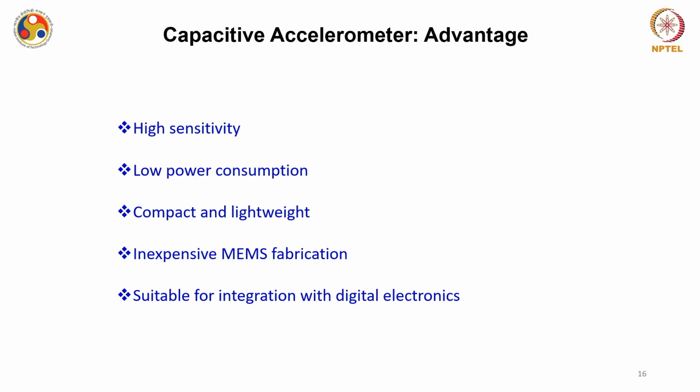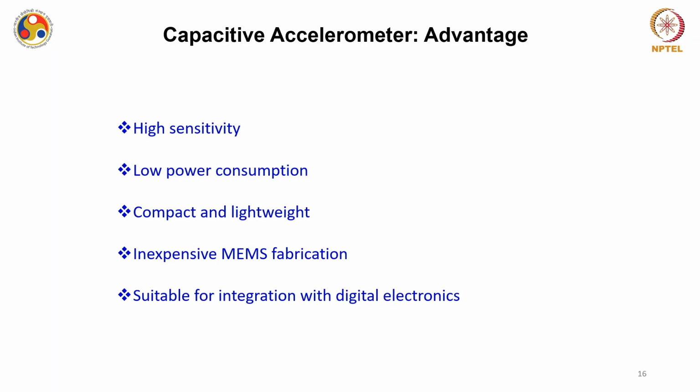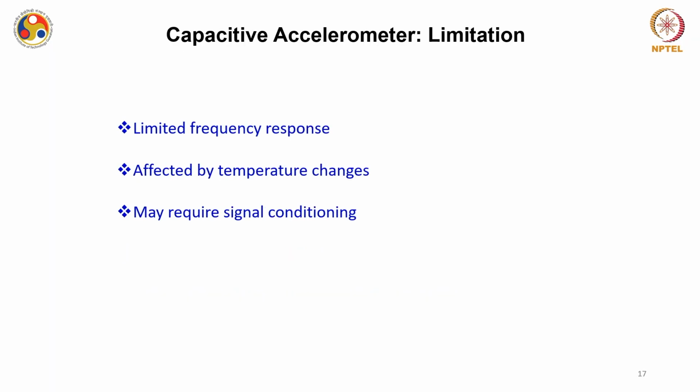There are several advantages associated with capacitive accelerometers, like their high sensitivity and low power consumption. They are compact because these are MEMS devices, and of course lightweight. Since batch fabrication is possible, they are mostly inexpensive, and they are suitable for integration with digital electronics.